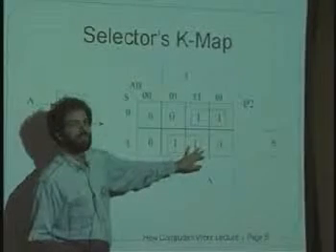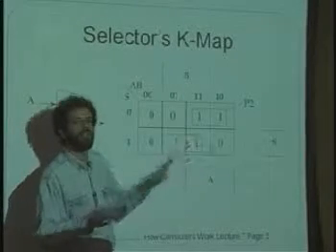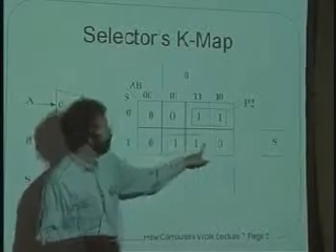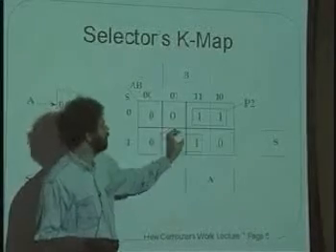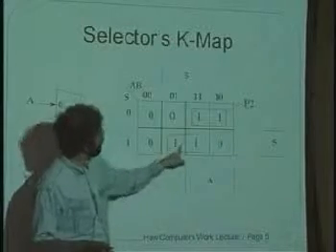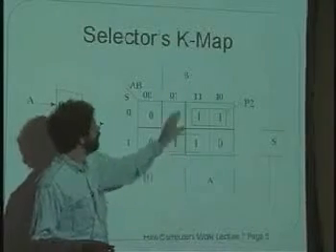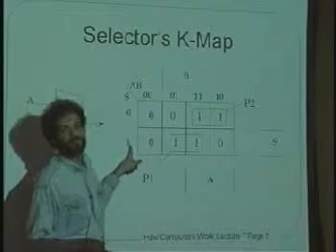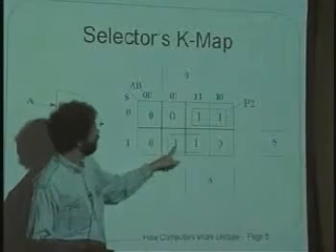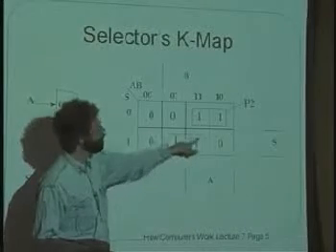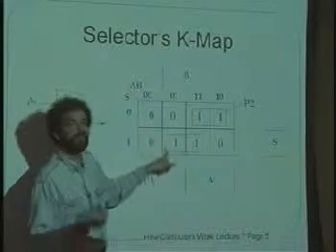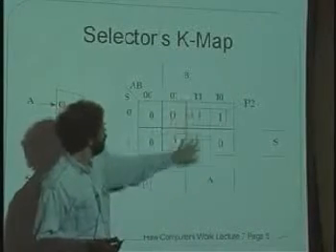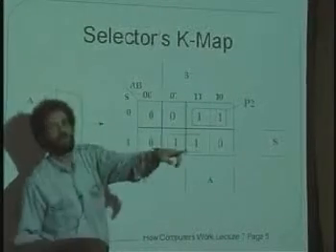But that group, 0, 1, 1, 0 doesn't stand for anything? No. Other than the individual elements, right. And then when we circle the two ones together, instead of separately. So if I were to just circle this one over here, this would be B and A bar and S. And that would be one way. But instead of doing that, I want to have a more simplified product term that has fewer inputs to it. And I circle both of them, and I get B and S, which is that lower AND gate there.